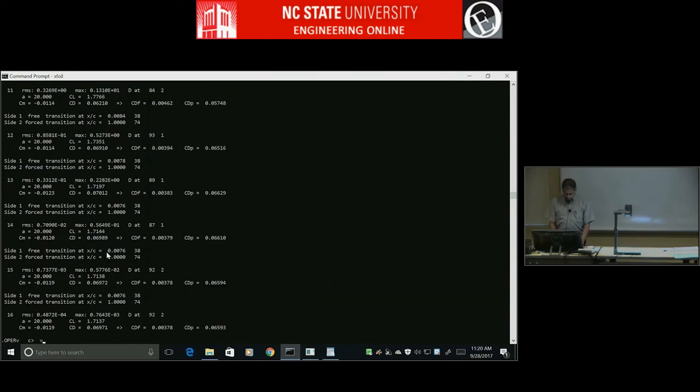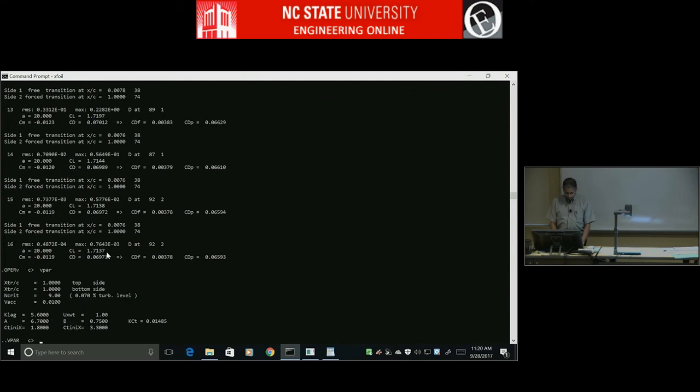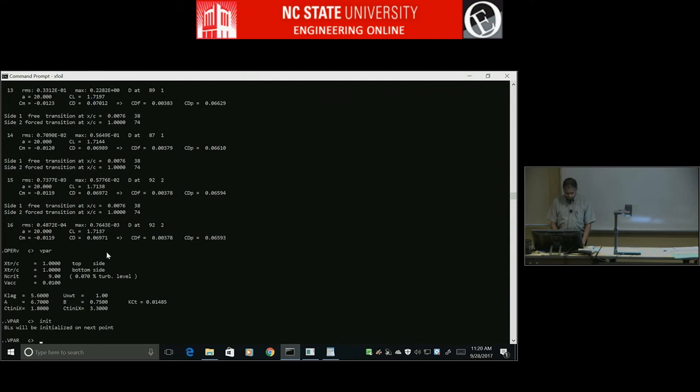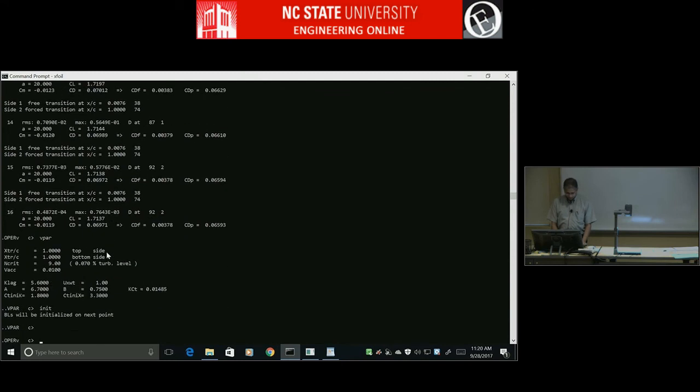Okay, let's run a sequence of angles of attack and talk about that other question. I'm going to do VPAR init, and then I'll do a sequence 0 to 20 in steps of 2.